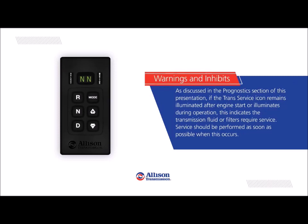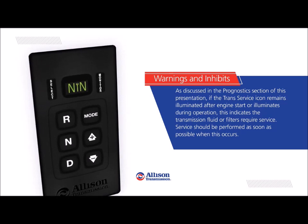Warnings and inhibits. As discussed in the prognostic section of this presentation, if the trans service icon remains illuminated after engine start or illuminates during operation, this indicates that transmission fluid or filters require service. Service should be performed as soon as possible when this occurs.